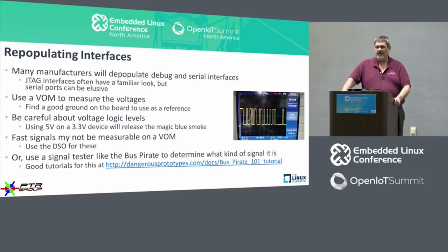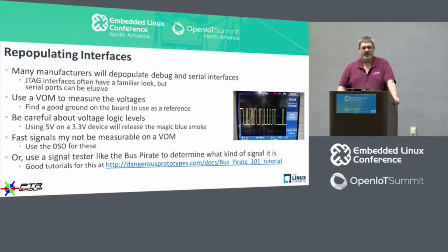In this particular case, this is actually looking at a communications channel, and what you're seeing there are ones and zeros going across. And also, because of what it looks like, if you actually could see it very well, you'd see that that is a little bit over 3 1-volt markings. So we were looking at 3.3 volt logic in this particular case.